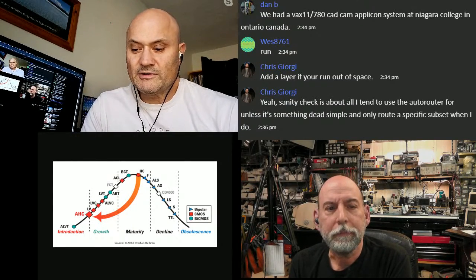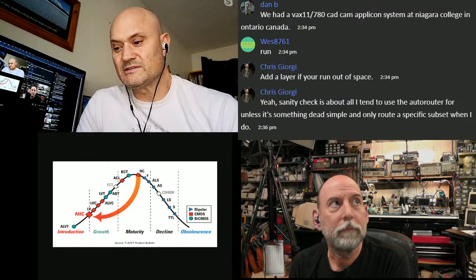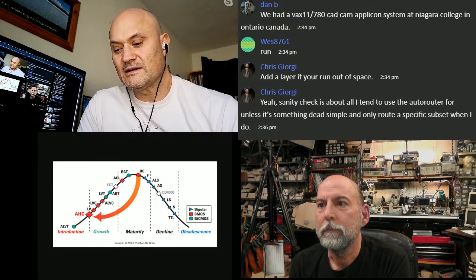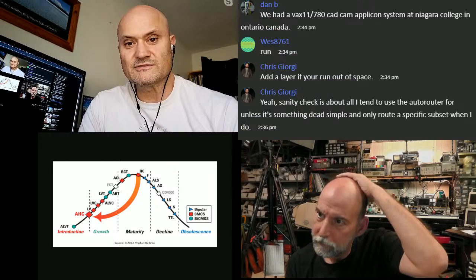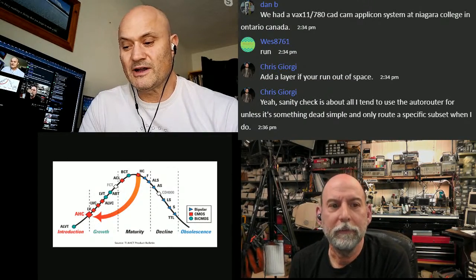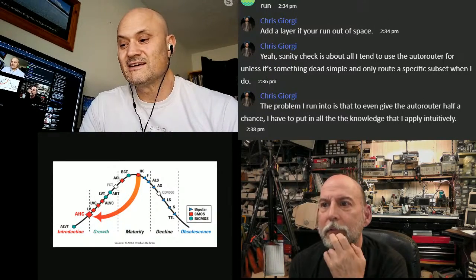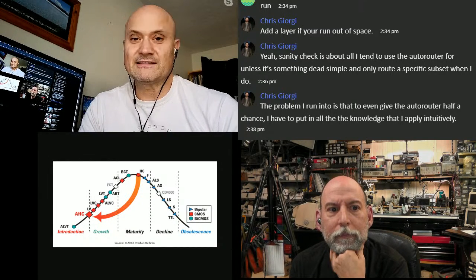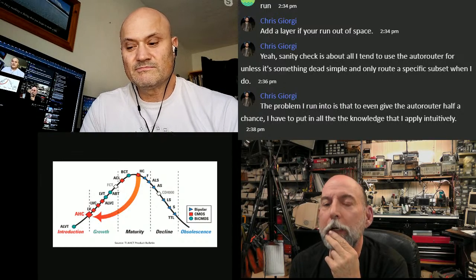Yeah, and that's another important point. Crazy results happen because people don't do enough design rules and setup. But there's kind of a balancing act there, because you can make your rules so strict that it will never be able to finish, or it might get to 60 or 80%, but then you'll do the rest by hand. And because you're doing the rest by hand, you're going to be pushing and shoving and moving things and rerouting them anyway. So at that point, you might as well just do the job manually.